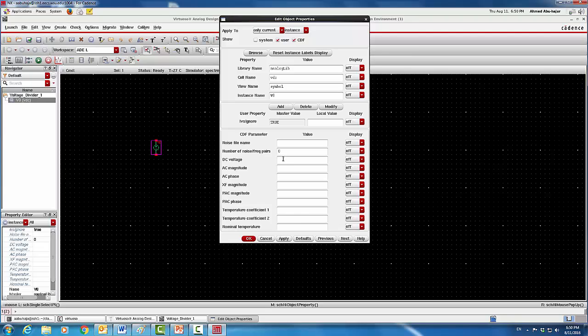All I need to do is add a value for this voltage source, and I'm going to add 1 volt. The rest of the parameters I don't care for. It asks, would you like to add noise to this voltage source? No, I won't. Usually noise is covered in senior year and graduate level courses, or is used by experienced engineers. Noise is a very important part in analog design and also in digital design, especially for IC designers.